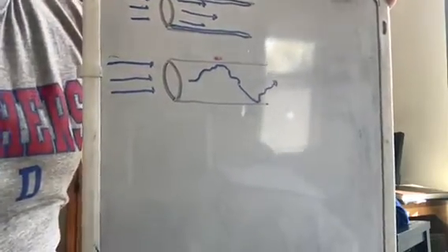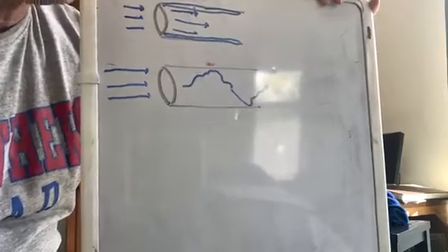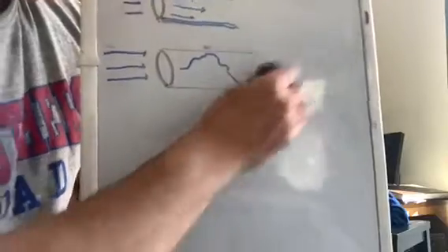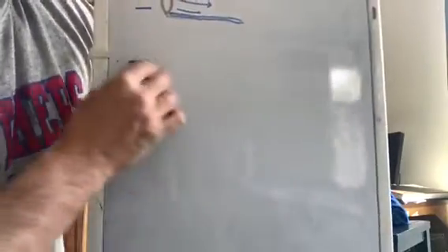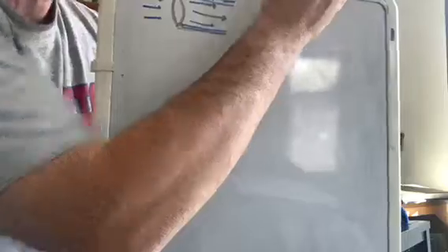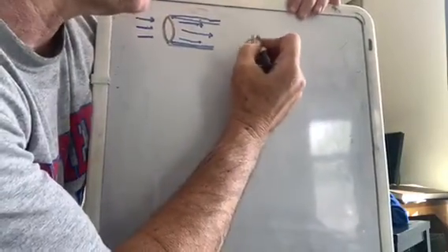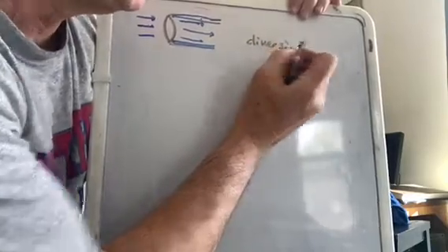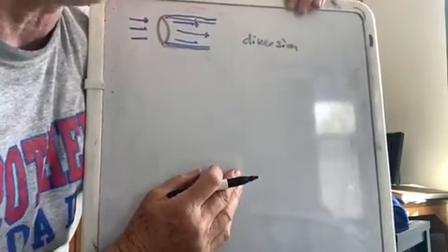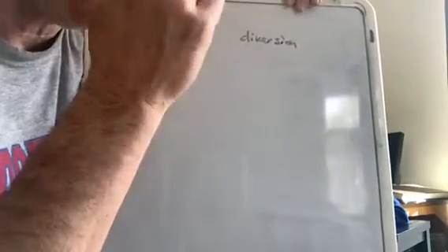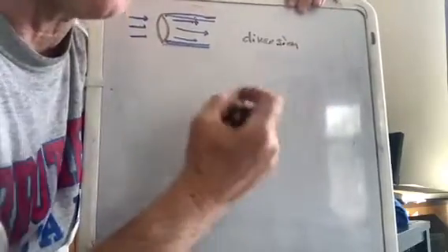So what we end up doing in order to decide whether it's turbulent is, in short, we're going to compare what are called the separation forces for a fluid to the cohesive forces. So separation forces or inertial forces, excuse my arm, that's usually the way you see it in the book. I would like you to sometimes think about it as diversion forces. Are there any forces in the situation which create diversion, the possibility of water diverting quickly, and that can lead to chaotic flow, chaos or turbulence. Chaos is too strong a word, but turbulent flow.